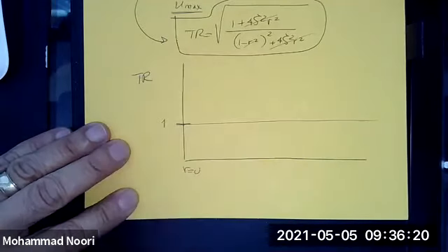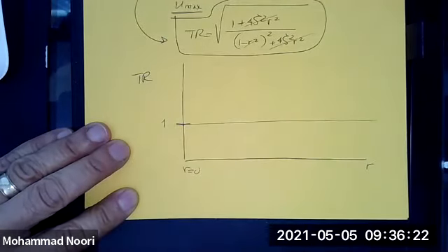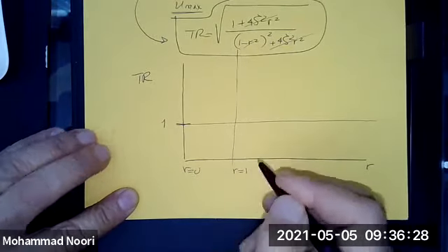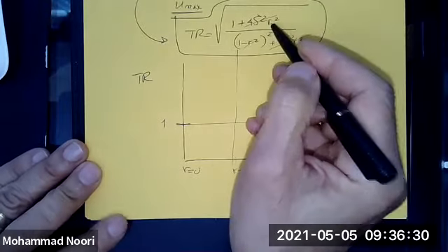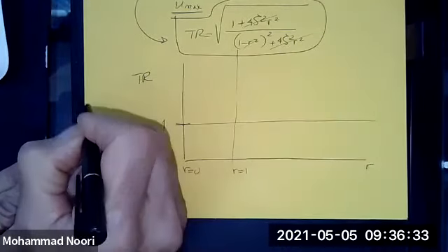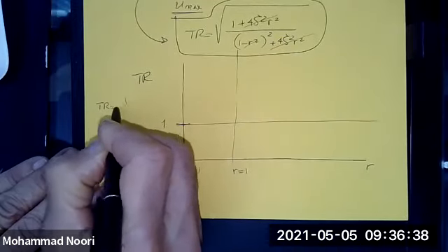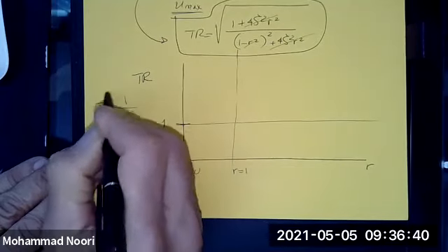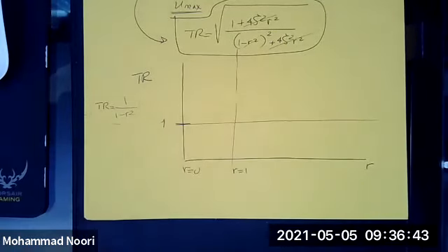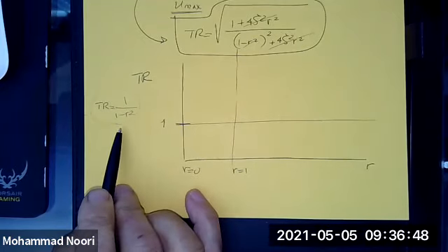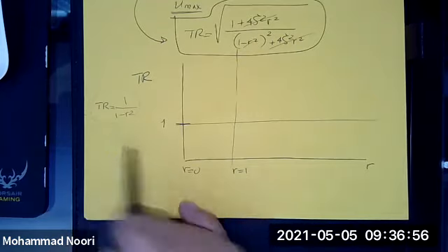So we are plotting transmissibility ratio versus frequency ratio. Now, if zeta is 0, what happens? Transmissibility ratio becomes 1 over 1 minus this. Does this look familiar? Yes, it does. This was the frequency response function for an undamped system subjected to harmonic load.